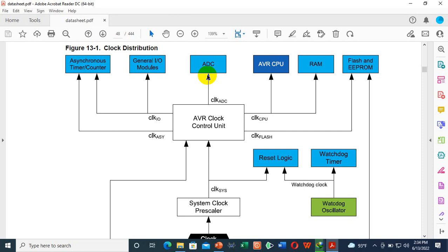The more frequency you use, the more accurate a result you will get. That means more sampling. If you sample more frequently, your data will be more accurate. So that depends on the rate at which you are sampling, and they use the 10-bit analog to digital converter. For the sampling operation and for the conversion, they need the clock signal.